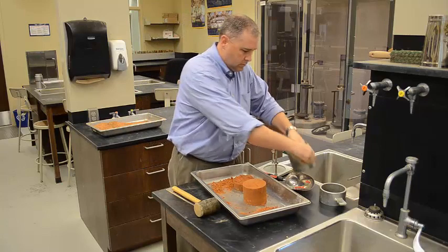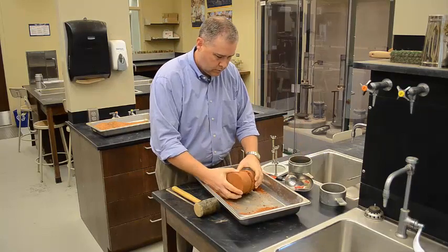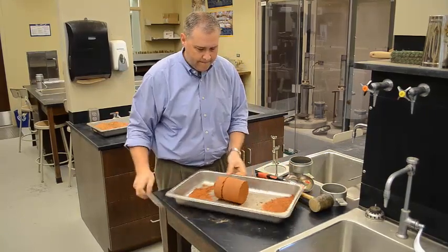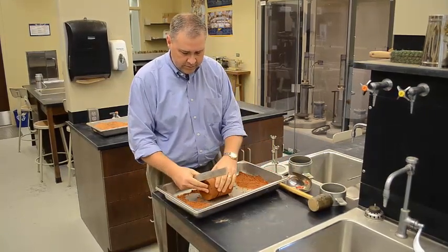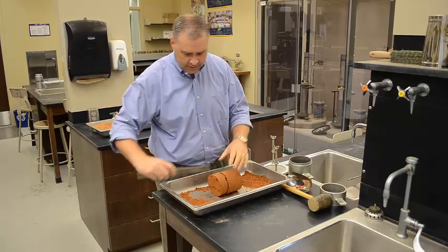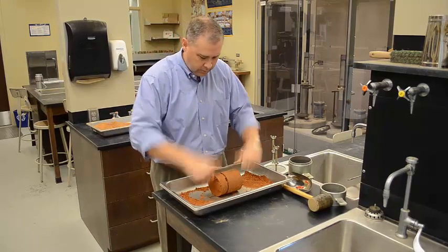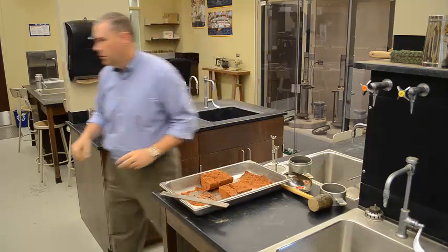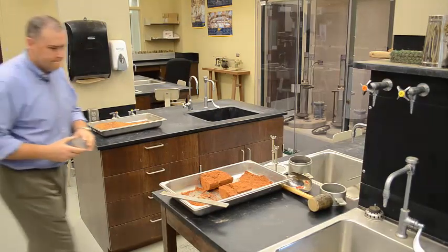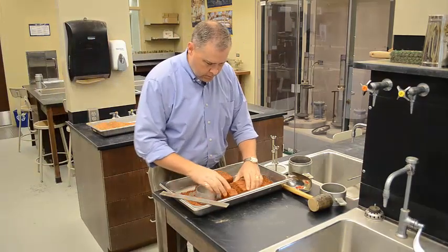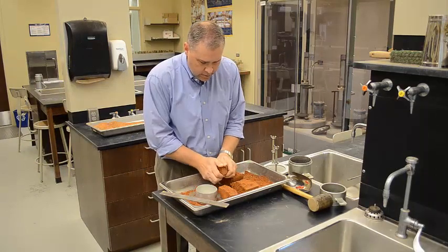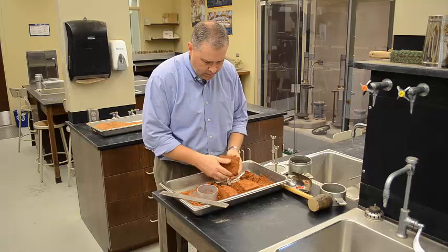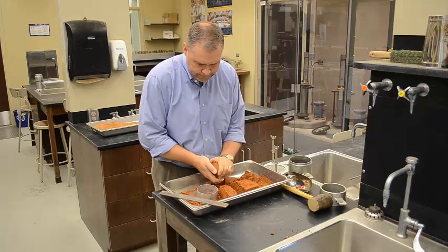Okay, and then once that puck comes out, you need to grab a moisture sample. So I put it back together a little bit because what we want to do is get a representative sample from top to bottom of that entire soil puck. So I place it like this, and I want to get it from the middle of that layer. So I grab my moisture can, grab the material from the center of that soil sample. So I grab a little bit from the bottom, a little bit from the middle, and a little bit from the top.